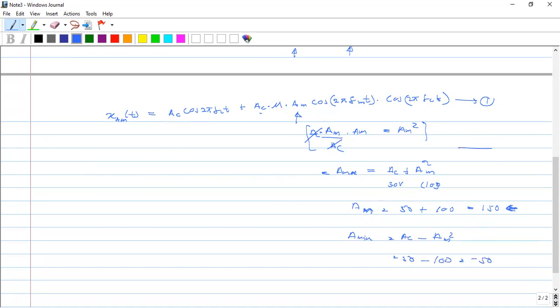If we draw the envelope in this case, it will start here, go and cross this time axis, and come back. Here it goes, crosses this, and comes back. So you will get this distorted signal. In the MATLAB program you can also see a phase shift at this point in the carrier signal. So this is wrong. It is over modulation.